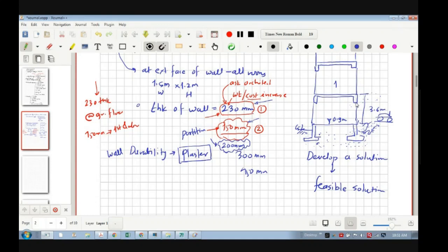Generally, if there is resonance happening due to certain vibration, see, it is a very rare case having resonance. So generally in RCC buildings, the column and beam sizes are very thick, and due to that thickness, if there is any sound vibration, the resonance possibility is very, very less due to the bulky nature of the building. There are walls, there are slabs, there are columns, so it is a very solid structure, you can say. So they don't have any issues regarding resonance in general. So vibration आया तो चलेगा, but they will not have any structural issues.